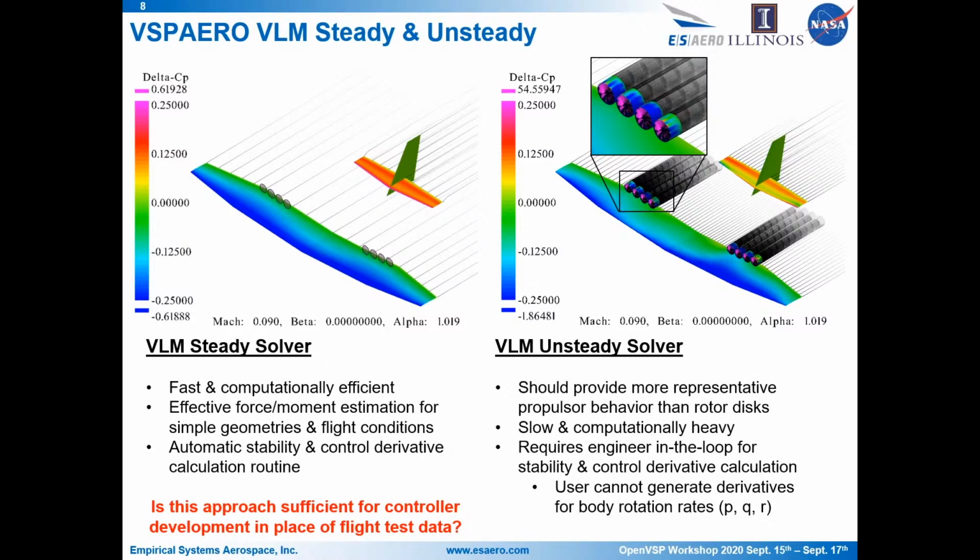And if your props are at several hundred RPM, then you're going to need to model several hundred revolutions to model that transition. And usually when you look at someone running, say, a full-on CFD, and they're doing a rotating rotor and time accurate analysis, they consider it a really big deal if they do 10 revolutions.